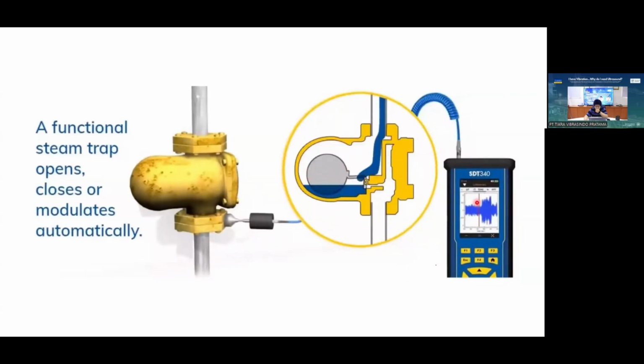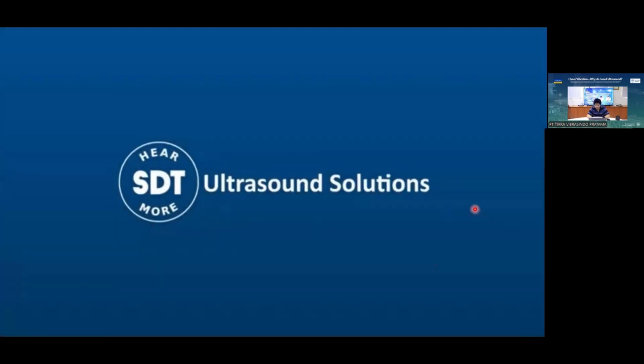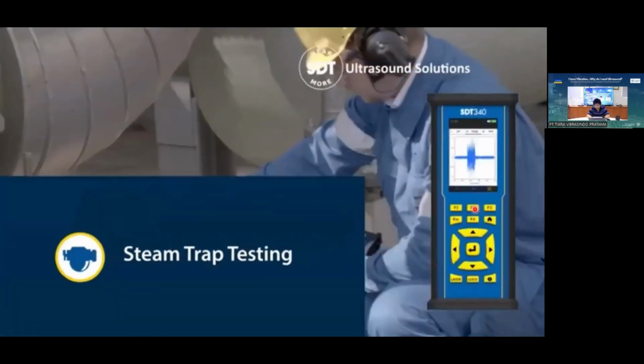When the steam trap is closed, you measure the time waveform here. When the steam trap drains the water outside, the ultrasound goes high. It's like open and close, open and close. It's not always open or always closed. You can see this video.